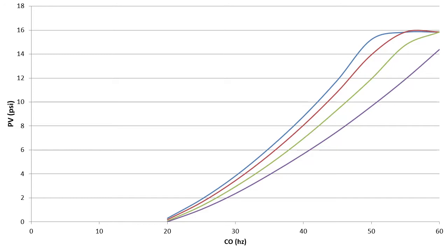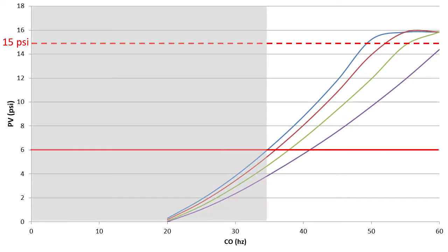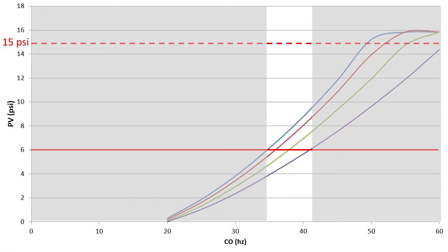Centrifugal pumps always require some minimum speed to operate, and in the quick start videos, we found for our system that turned out to be around 20 Hz. At the top end, we maxed out our 0 to 15 psi pressure sensor before getting to the full drive speed for 3 of the loads, so things go non-linear past this point. We want to maintain 6 psi, so we really only need to operate the motor between roughly 35 and maybe 42 Hz. But we don't want to limit PID to that range. We want to give PID as much motor range as we can.